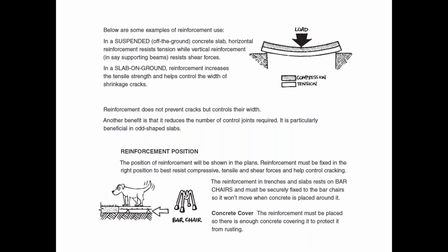And for those that have never seen this before, you have what's called bar chairs or rebar chairs, and they come in different heights. So you can rest all your reinforcing at different heights or different spacings around the place. Handy to know. And remember, reinforcement doesn't prevent cracks, but it helps control them and reduce them.